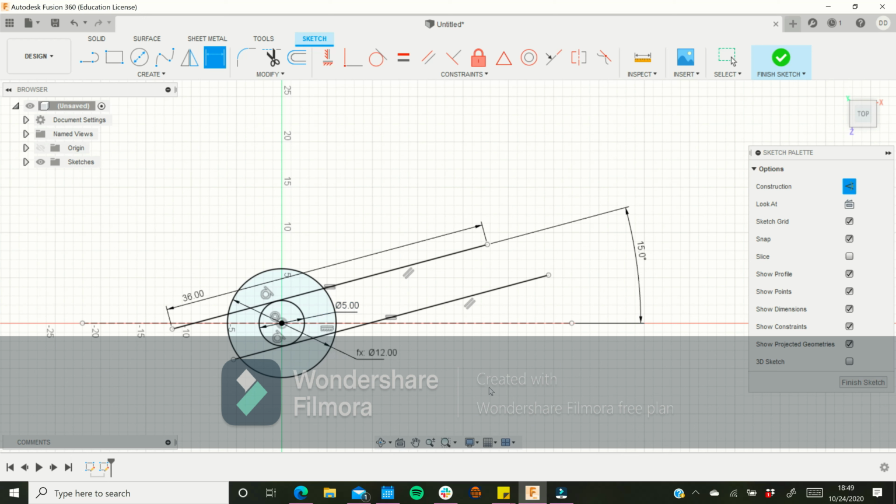It'll always be 7 inches more than that one. If I wanted it to be 12 inches at all times, I could always just set this to be 12 instead of being a function of something else. But because we've gone over functions within dimensions, I figured I would do that. So yeah, now as you can see, everything is black, meaning it's all constrained, and I can't click on anything and move it anywhere. And well, I can do that, I guess, but that doesn't really matter.